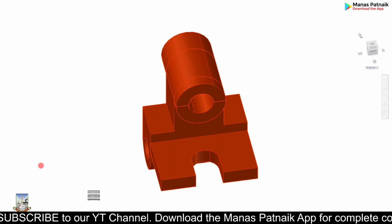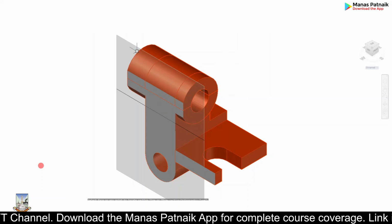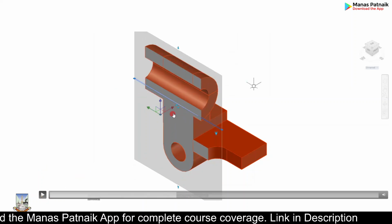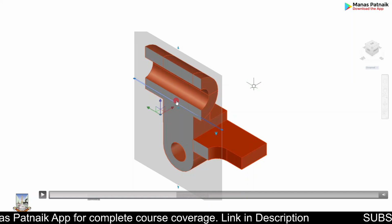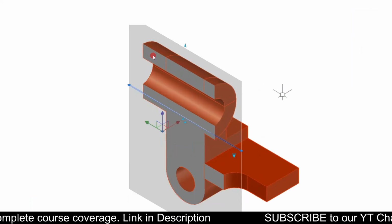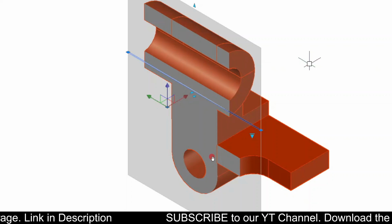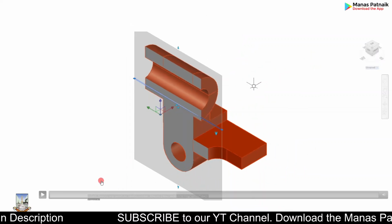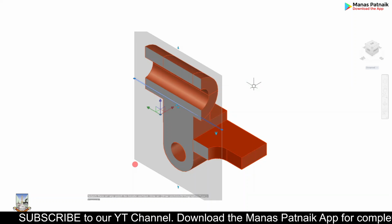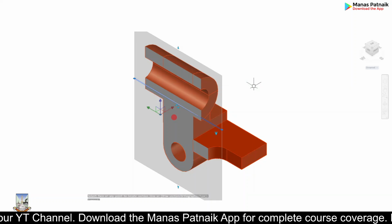What we'll do now is we are going to have a cutting plane, popularly known as a section plane, and let me get the section plane passing through the center. Exactly. What you see over here, the portion of the object which has come into contact with the section plane is what is known as a section. This grayish portion is the section, and you need to draw the section by watching the object from over here. This is your front, as far as the problem description is concerned. So in the front, the section can be seen, and hence we call this a sectional front view.